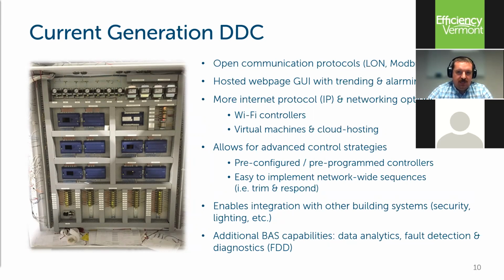With these open communication protocols too, it became easier to build out our networks. We required less and less gateway devices. A lot of the time we even have the ability to go straight from a terminal controller like a VAV right up to a server with no supervisory controllers or gateway devices needed because it's all IP based now. Our programming tools and our devices now become much more universal.